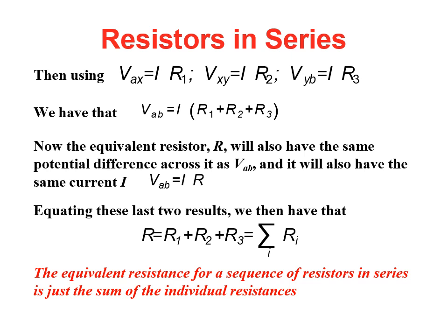In Ohm's law, we learned the formula I equals V over R. So we can use that same formula to calculate the voltage drop across resistor 1. VAX, the voltage drop across resistor 1, will equal the current I multiplied by R1. Then the voltage drop across resistor 2 would be VXY equals I, the total current, multiplied by R2. And lastly, for resistor 3, VYB equals I times R3. And we know that these resistors have the same current, which is I.